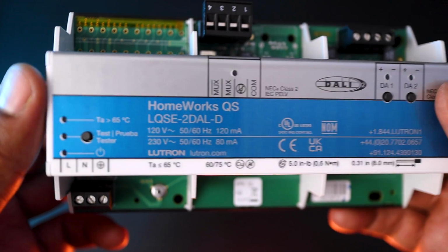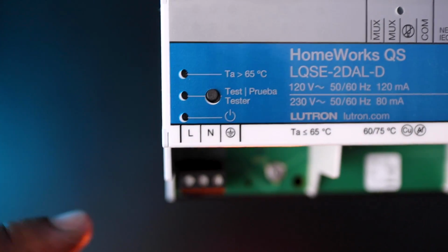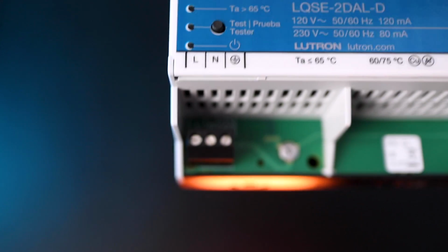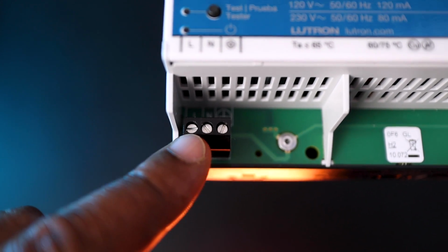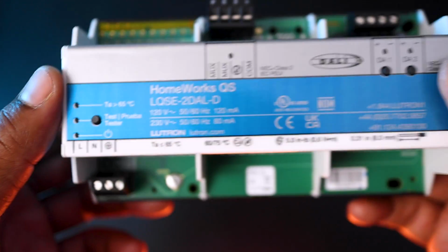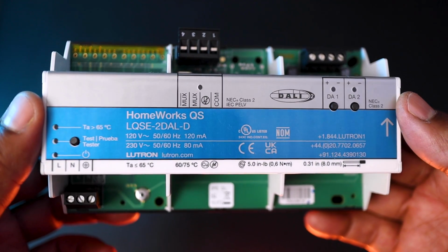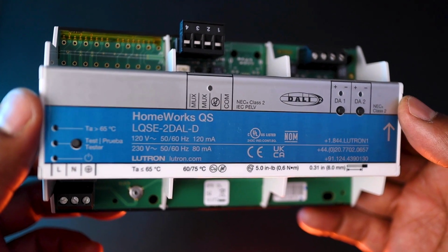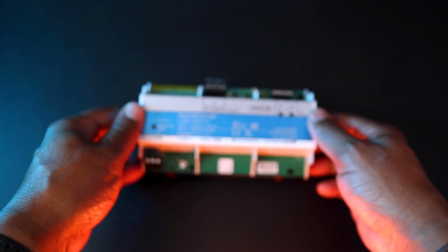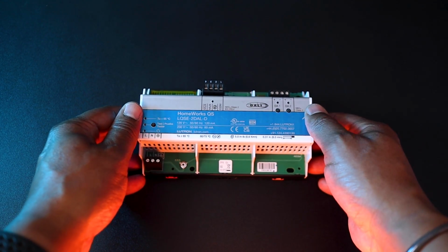That's one of the great advantages of using a DALI control system. Again here, we need to bear in mind that although the DALI module will be mains powered from this connector here, it will not power the DALI light fittings. As we said before, the DALI light fittings will have to be permanently powered directly from the distribution panel.